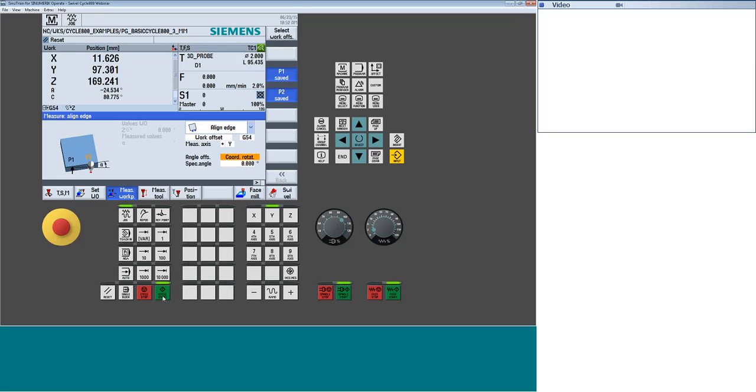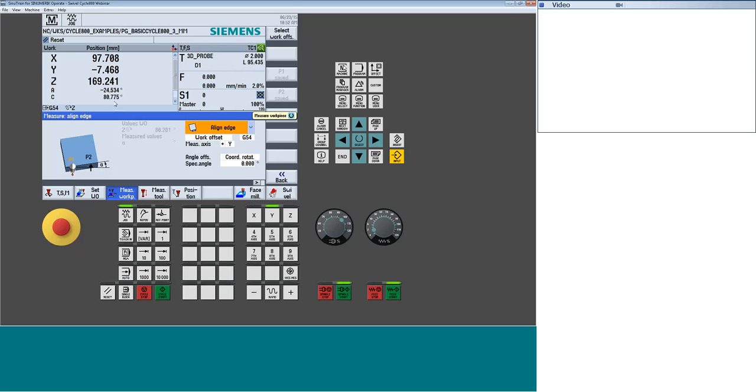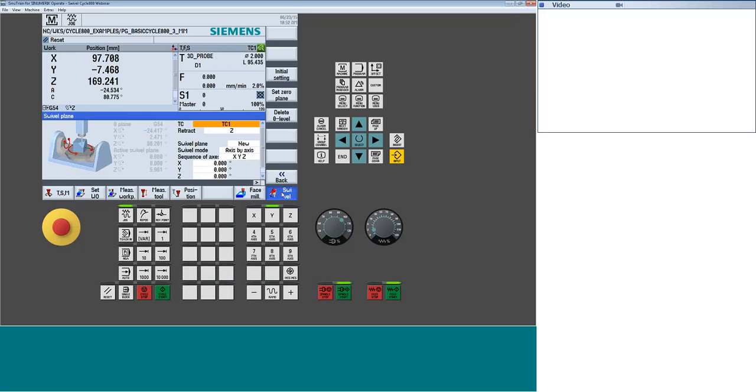All right, I set my work coordinate. And that writes this value in. So if I go to the offset table, I now see there is a new value under the Z. So if I was to now instate this new offset, see we're at 86.2, originally we were at 80.775 and 24.5. So now I go back to swivel, I cycle start, and now we are 0 to this new location.